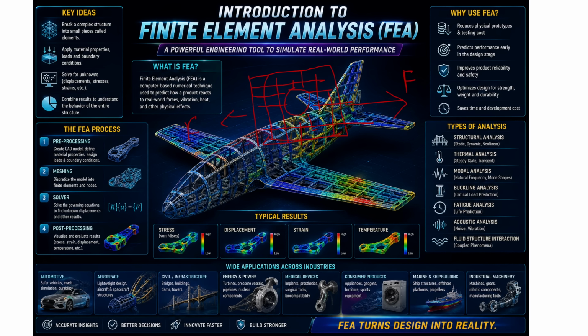So instead of building a physical prototype multiple times with different load conditions, we can apply the same thing in the virtual world, in the software, and combine these different loads and stresses generated in the plate, and we can derive our conclusions from it. So that is the key idea behind FEA. It breaks a complex structure into small pieces called elements, applies material properties, loads and boundary conditions, solves for unknown displacement, stresses, strain, etc., and combines the results to understand the behavior of the entire structure.